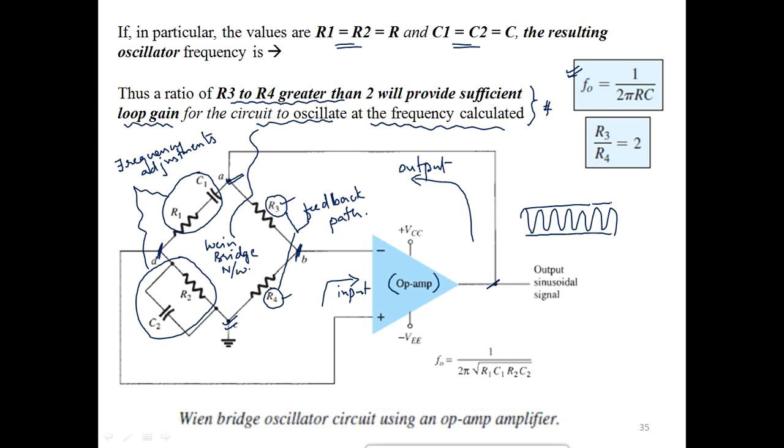The phase shift cannot be controlled properly, and tuning of the output at a particular frequency is not so easy in the case of RC. This can be better controlled by replacing RC with LC. RC is simple, but it is not so efficient with respect to frequency tuning.